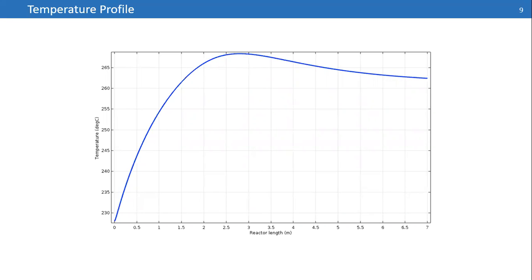So my question is, when you are going to work on a reaction system and the reaction is exothermic, you are not just going to increase temperature. You cannot decrease temperature lower than a specific temperature either. For example, for a methanol reactor, the operating temperature is around 250. But what if I work at, I don't know, 400? You will have the problem of thermodynamics. What if I work at, I don't know, 150? You have the problem of kinetics.